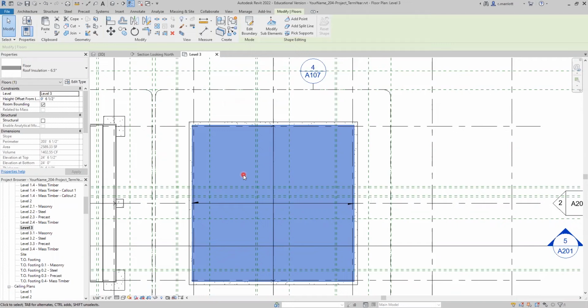You have backup. Sometimes we detail something called a scupper that basically sends the water, if it gets to a certain height on the roof, out around the perimeter. There's a number of different ways of doing it. You can also do an overflow drain. But what I'm going to show you is how to split a roof so that you can have 2 areas that include the drains.